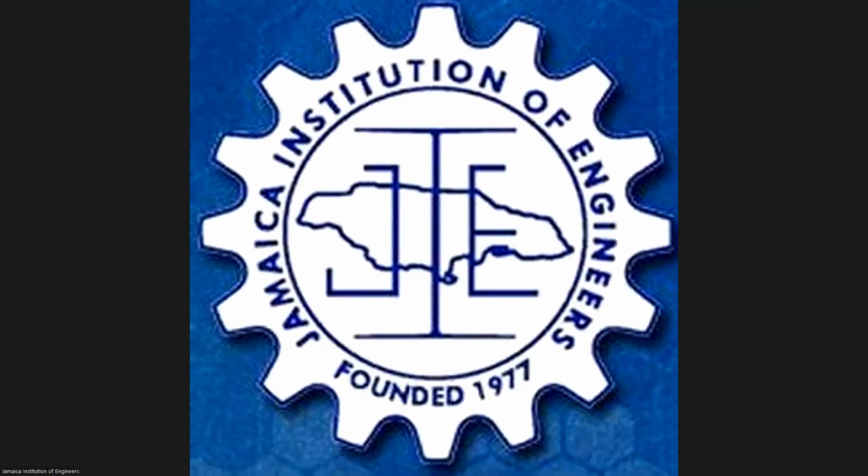Great. I hope that answers that comment. I hope so too. This person is asking you just to repeat the specifics surrounding the 60% occupancy requirement for water supply. All right. We prefer 60% occupancy, meaning that water is being utilized, potable water is being utilized, and sewage, if sewage services are at that particular development, sewage is being discharged. That allows the old water in the pipes to be used and replaced.